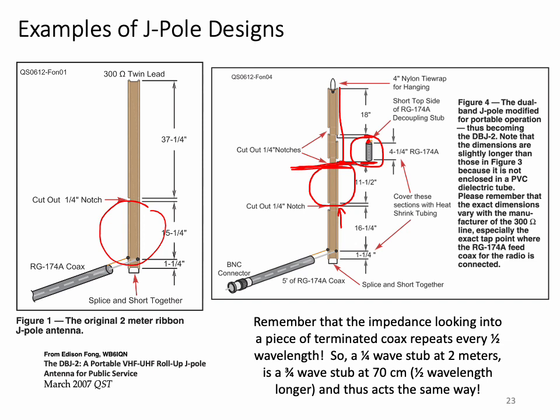And so the 2 meter portion of the antenna looks as if it's the composition of these 3 sections. It's a section below, which is the half wave dipole for 70 centimeters, the quarter wave stub for 70 centimeters, which was used to choke off the 70 centimeter antenna from the rest of it. And then the rest of the antenna is sufficiently long in order to let this entire length be a half wavelength on 2 meters.